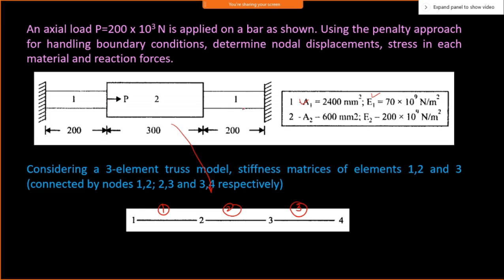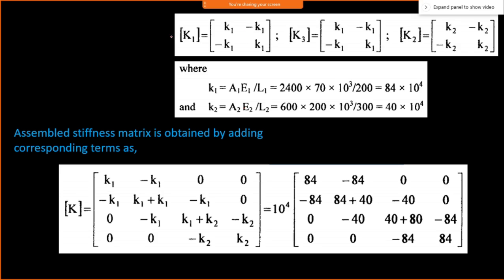And you can now solve. So you can get a stiffness K1 here, K2 here, K3 here, all these three stiffnesses. Okay, K1, K2, K3. Then assemble it. This is nothing but a common node where it is going to be added. So these are the two places where it will be seen to be added. So this is what you got: an entire assembled stiffness matrix, we can say global stiffness matrix.